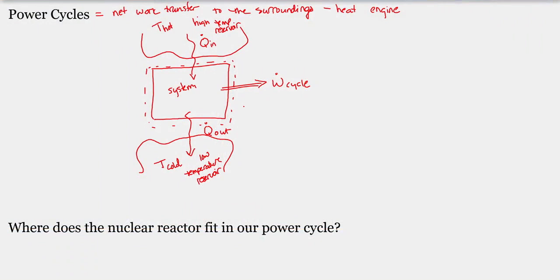Okay. We know that as we move that steam through the turbine, we go from a high energy state to a low energy state. And then we want to close this loop, so we take that low energy vapor and we condense that into a liquid. And in order for us to condense the water, we need to remove heat from that working fluid. And that's this portion of the power cycle. So we reject heat out of my power plant and into some cold temperature reservoir. Okay, so that's the generic description.